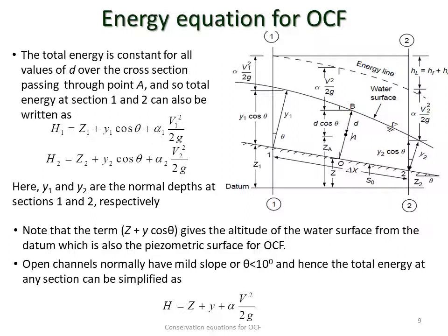Also note that the term capital Z plus Y cos theta, in the figure, gives you the altitude of the water surface from the datum. So in the context of open channel flow, the water surface elevation gives you the piezometric head. That is mathematically given as Z plus Y cos theta.